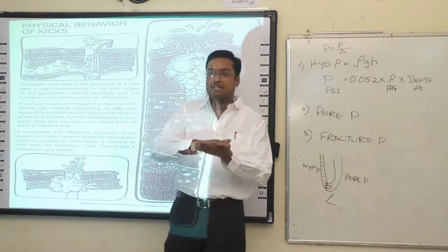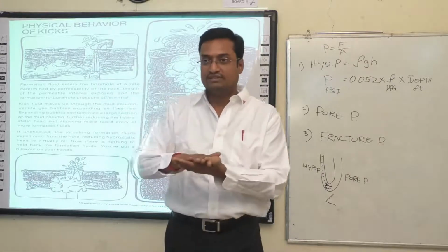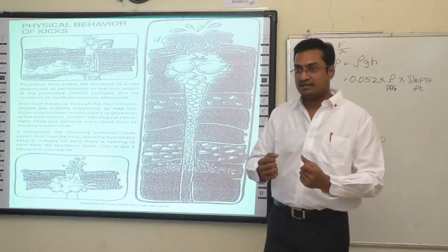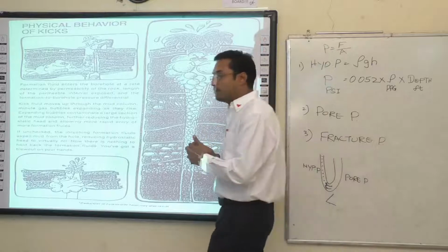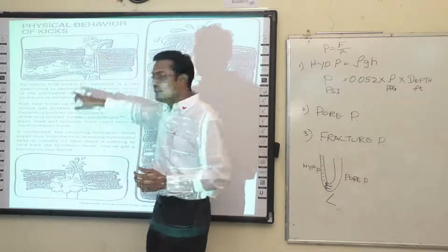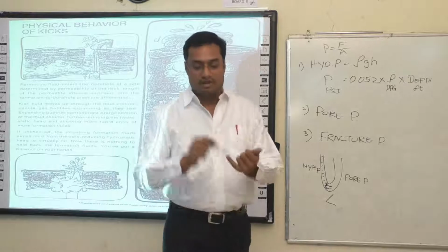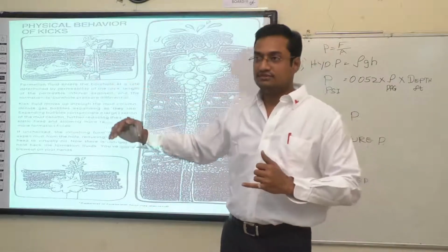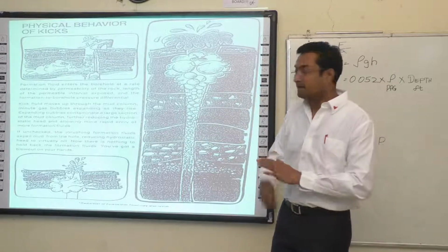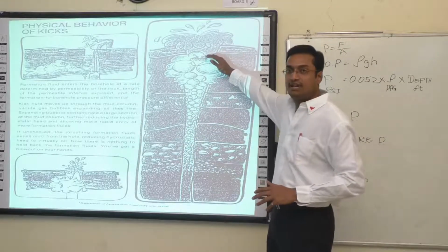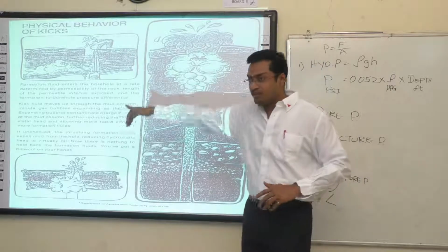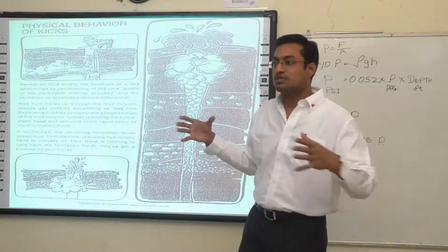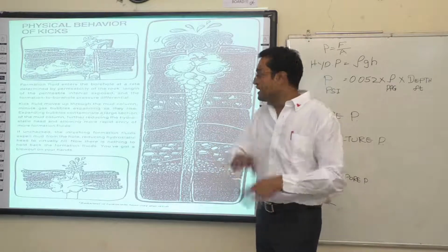If the hydrostatic pressure is maintained by the drilling fluid, it is always balanced or more balanced. So there is no kick. So the primary well control barrier is the drilling fluid maintained in the wellbore with correct density and keeping the hole full. So the drilling fluid is a primary well control barrier and the BOP is a secondary well control barrier. So if you lose the primary well control barrier, you get into a kick. To control it, you use the BOPs and you circulate out the kick.